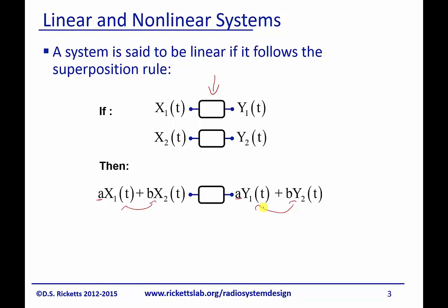The basic way to check is this idea of linearity. If I put in one input, and the example I usually use is I just double the input, do I get double the output out? If the answer is yes, it's linear.